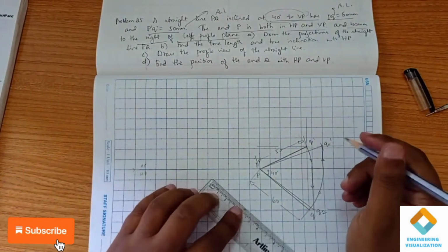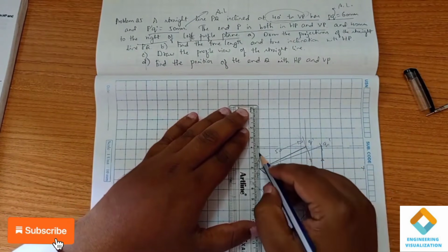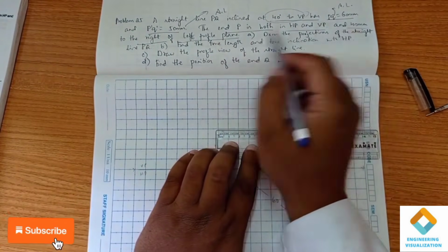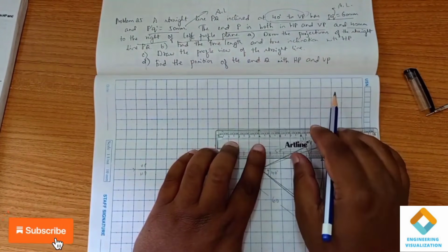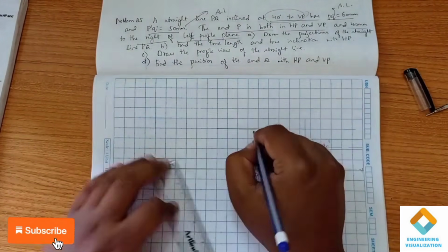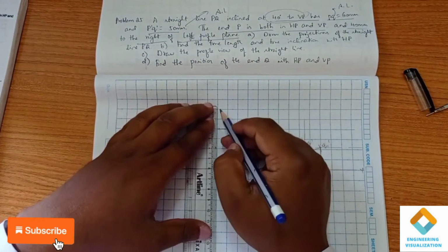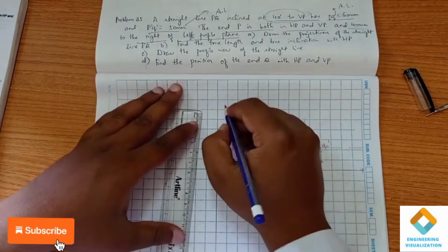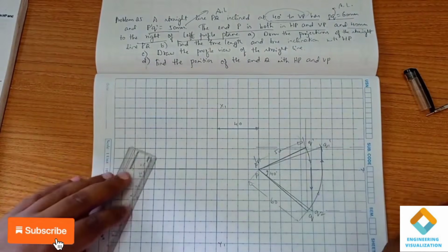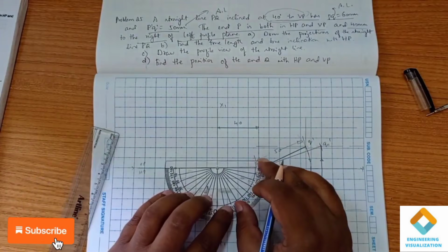Now from this end we'll be drawing a line of 40. You can see here, 40 mm from the right or the left profile plane. So here we're going to draw another line, so this is x1 and y1. For the top view I'm going to draw a 45 degree angle line.